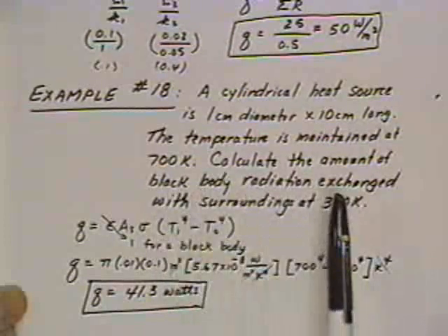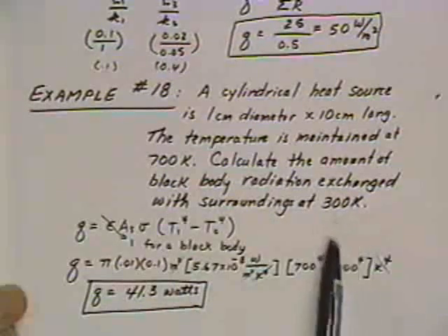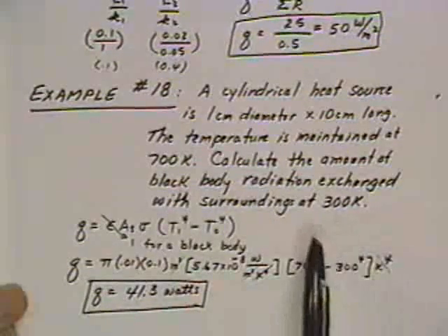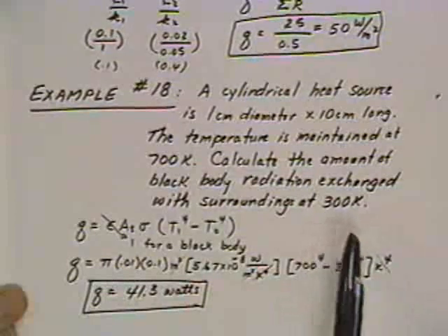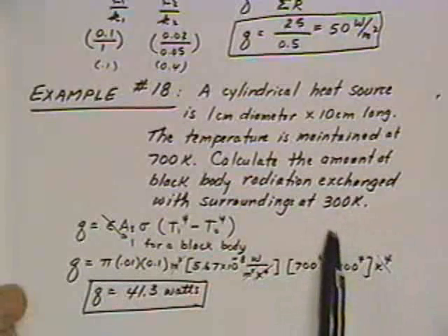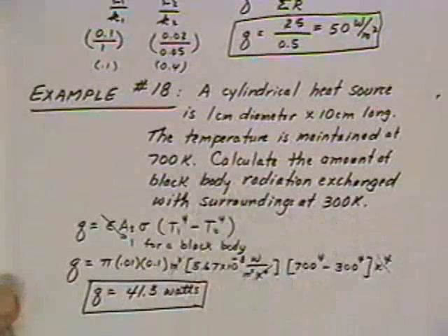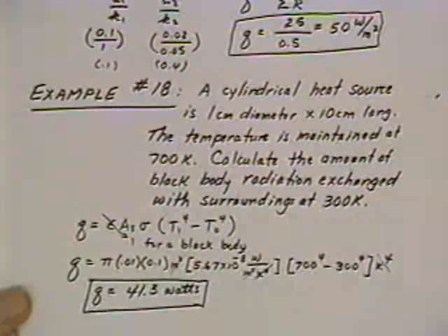And so we've got an equation. The principal thing in dealing with radiation heat transfer is that you're working with the 4th power of the absolute temperature. And so again, another admonition, make sure that you're converting your temperatures to absolute temperatures. In this particular case, I made it easy because I gave them in degrees Kelvin to start with.